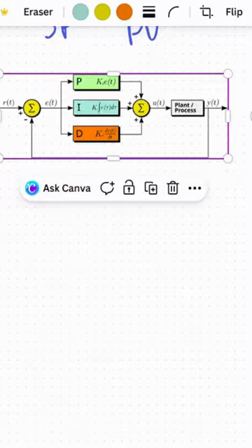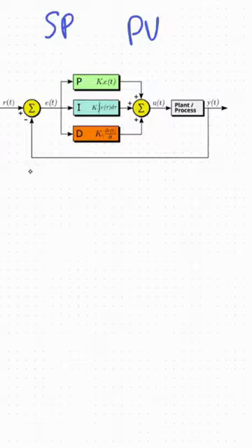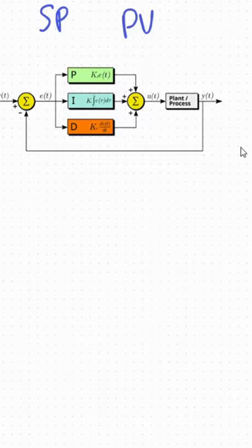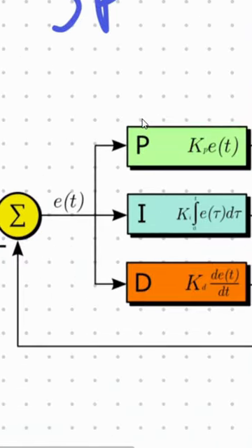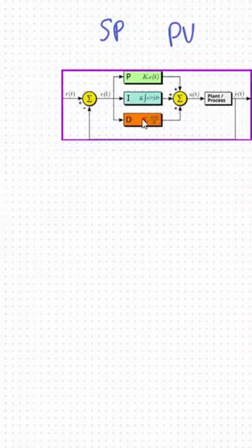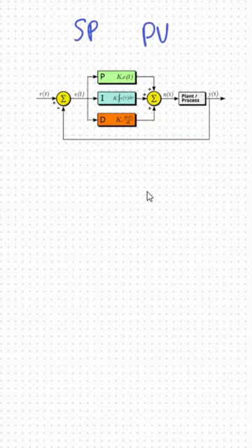It shows a PID controller which continuously calculates the error value e(t) as the difference between SP and PV and applies a correction based on the proportional, integral and derivative terms. So the controller attempts to minimize the error over time by adjusting the control variable, which can be opening of a control valve, adding a new value to the weighted sum, etc.